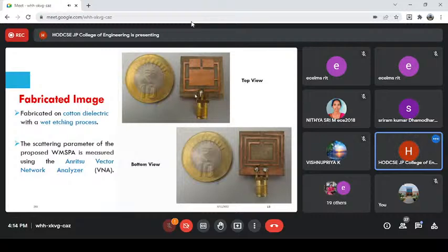It is almost a late 2021 research work, sir. The sub-7 gigahertz range has only now been introduced and added to the IEEE standards. Very good. So this antenna is designed and fabricated for the sub-7 gigahertz frequency range. Millimeter wave has very high throughput and high speed, but it has one major disadvantage, sir: obstacles completely collapse the entire performance. That will be rectified by using sub-6 and sub-7, sir.